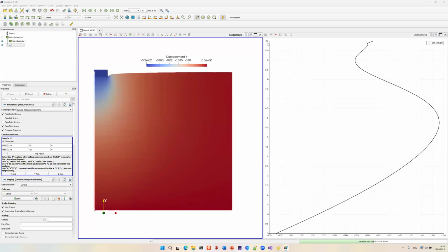Yeah, I mean, you can do that. Bearing capacity, let's say with a Mohr-Coulomb model, for such simulations I would rather maybe go to Mohr-Coulomb or something like that. And yeah, one can do that. You will have, as in all the other finite element simulations, the question of discretization, if you are really interested in shear bands. If you want a proper discretization of the shear bands, you will have to use a fine mesh below the foundation.